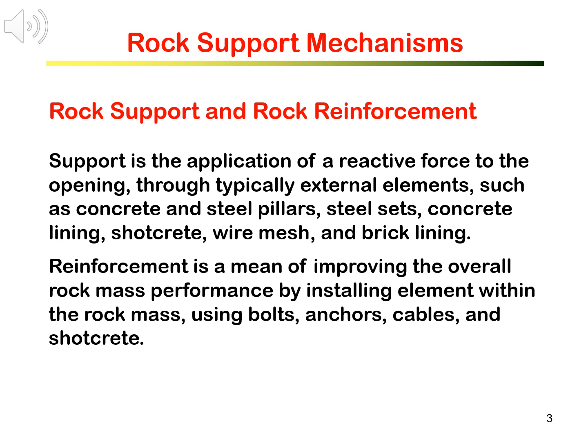Reinforcement is a means of improving the overall rock mass performance by installing elements within the rock mass. It is similar to using steel reinforcement in concrete to improve concrete strength and the resistance against tension. In rock mass reinforcement, we install steel bolts, anchors, and cables into the rock mass to strengthen it. We also use shotcrete and cement grout to fill the rock joints and increase the joint strength.